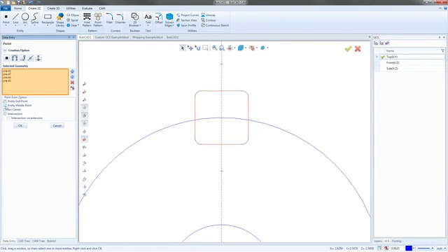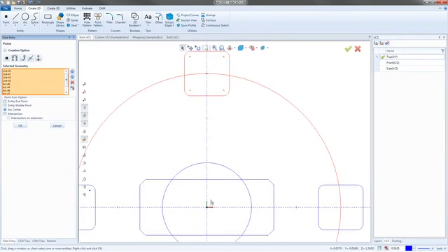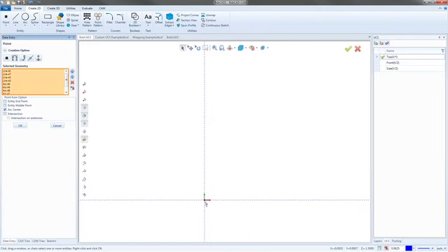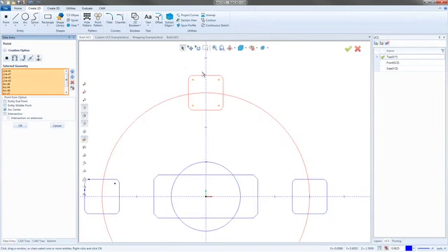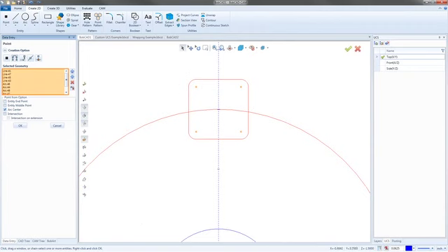The other ones we have in here are like the arc center. So if I go ahead and pick this right here, I'm just going to pick all four of those, as well as this big arc right here. And if I say arc center, what we'll see is the points show up for all the arcs there, as well as, you can't see it, but there is going to be a point. It's very faint. There's an orange point there in the center of the main arc, which is the 3-inch radius arc there. And so we have our center points.